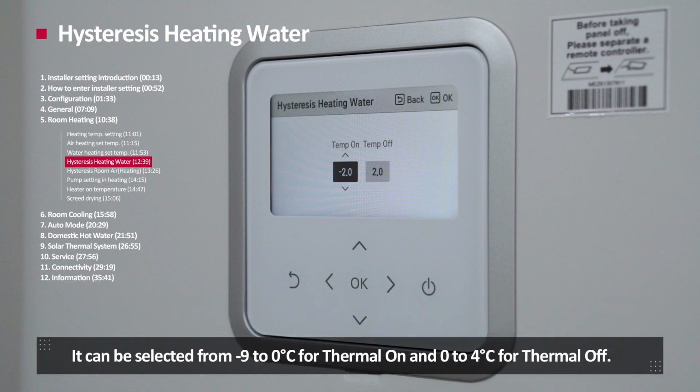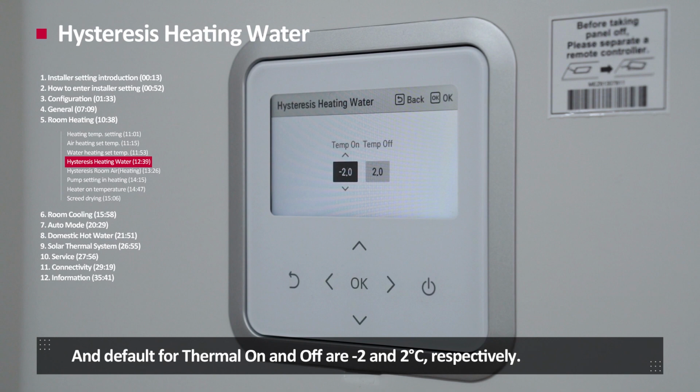It can be selected from -9 to 0 degrees Celsius for thermal on, and 0 to 4 degrees Celsius for thermal off. And default for thermal on and off are -2 and 2 degrees Celsius respectively.